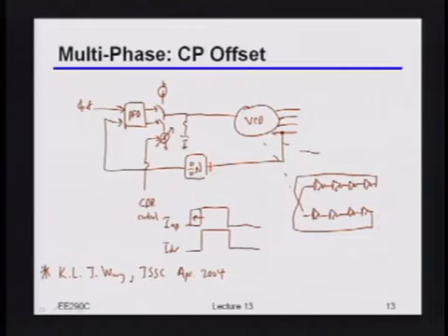Yeah, okay, so the real trick is that basically you can't really tell the difference between hacking on this and just changing the phase of the reference. So effectively the transfer function you're going through is the same transfer function experienced by the reference. So to the extent that this loop bandwidth is pretty high in comparison to your CDR loop, it doesn't make a big difference. Now you're absolutely right that if I wanted a very high CDR loop bandwidth, then this would be a problem, right? Because it introduced additional filtering and phase shift, etc., into my CDR loop. Does this make sense to people, or?